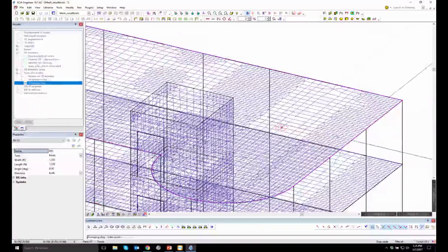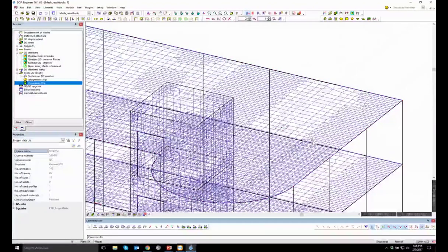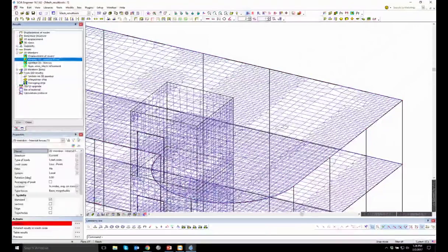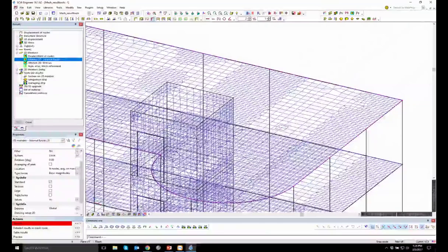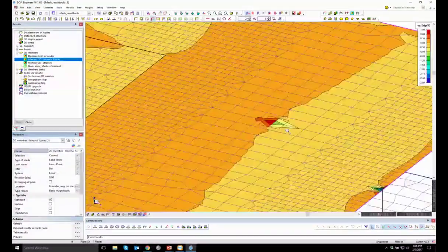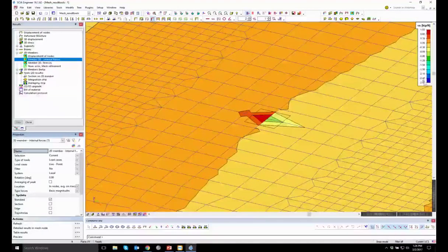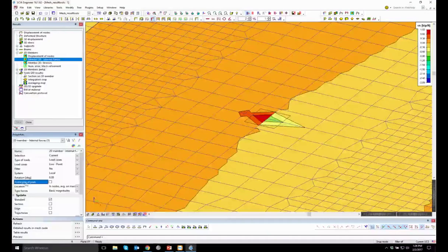First I have to select the slab. So let's select the slab here, and then we can go ahead and apply it there. So now effectively we have that averaging strip. If I go back now to the internal force, we can review that same internal force again. So this is the internal force that we had, right? Let's zoom in here. Somewhere on the order of 1.03 kips per foot, and probably between 0.6 and 0.9 kips per foot.